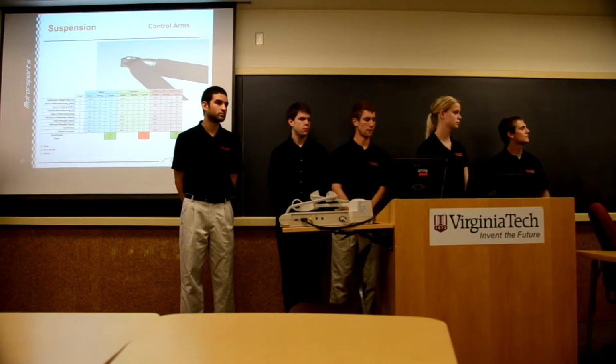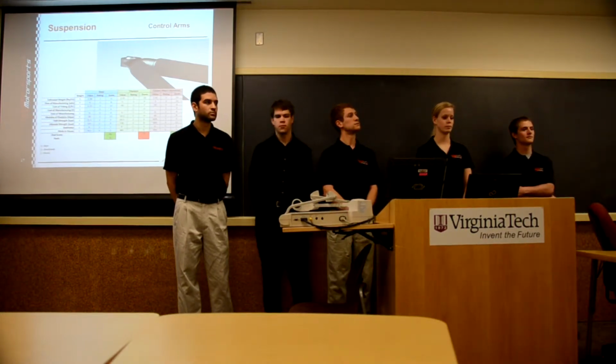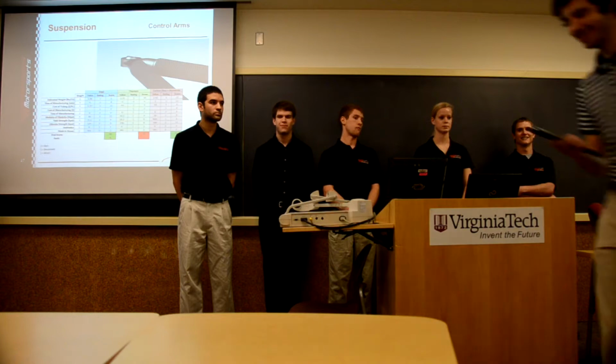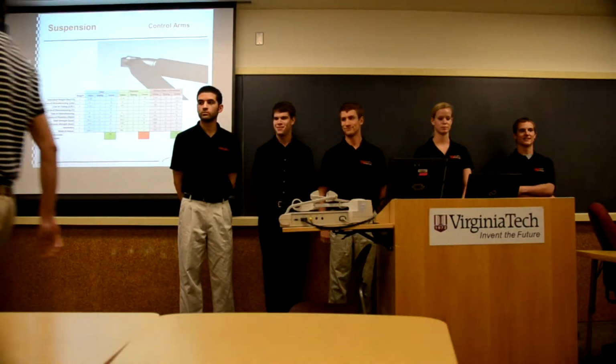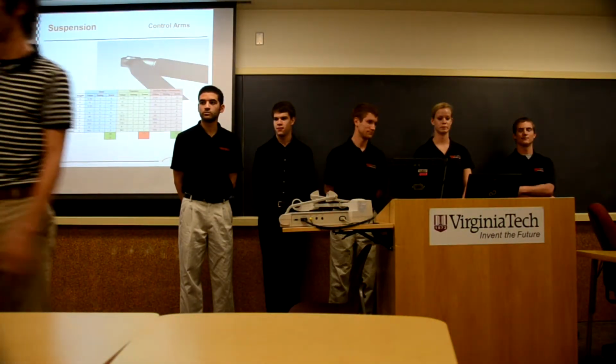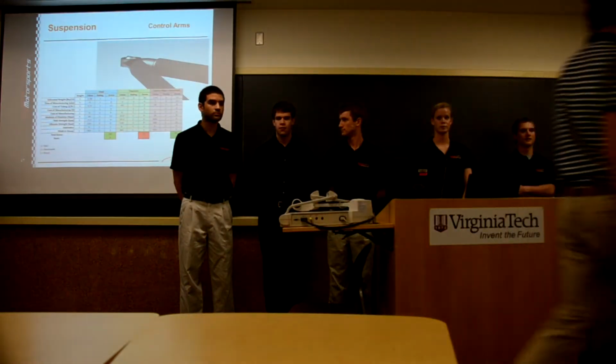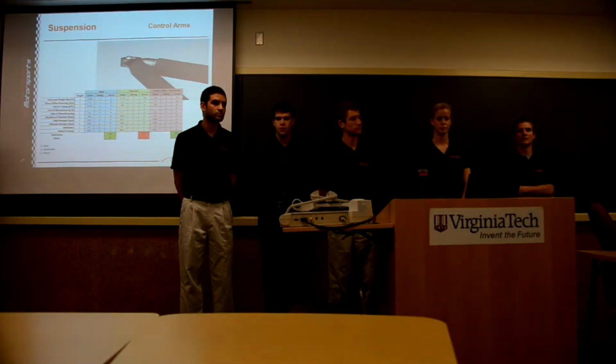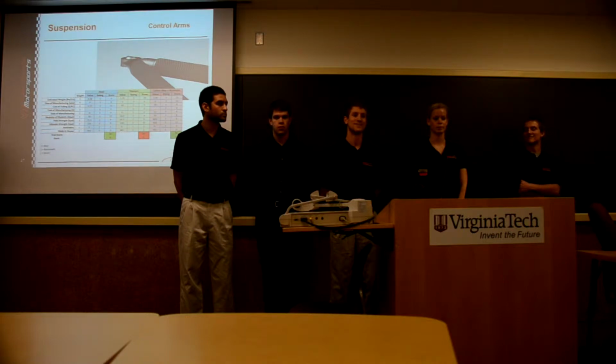Alright guys, so I'm going to talk about the control arms. I brought a few props with me. My biggest thing is I'm thinking of switching to carbon fiber versus steel. And obviously, I'm sure a lot of you guys have seen this stuff before, but when you put it next to each other, it's pretty impressive. I'm thinking in the tubes alone, we could save 50% of our mass. On the system as a whole, 20 to 30%.